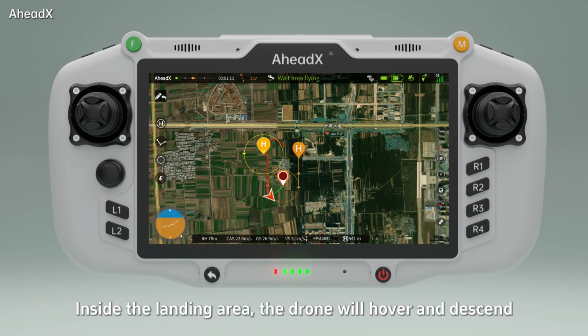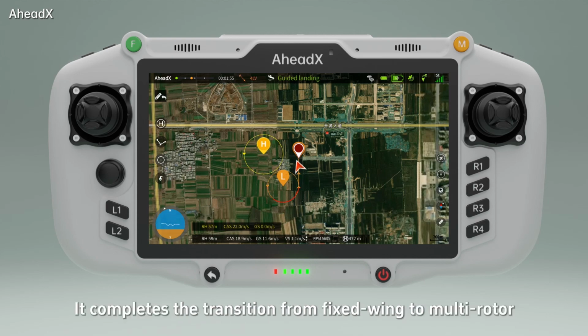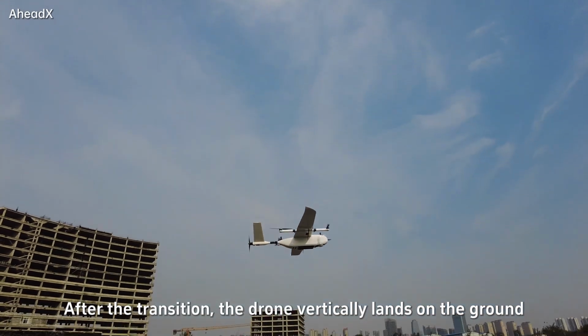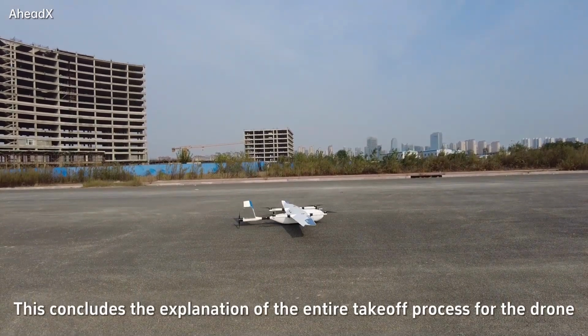Inside the landing area, the drone will hover and descend. After reaching the set altitude, the drone will fly to the landing point. Above the landing point, it completes the transition from fixed-wing to multi-rotor. After the transition, the drone vertically lands on the ground. This concludes the explanation of the entire takeoff and landing process for the drone.